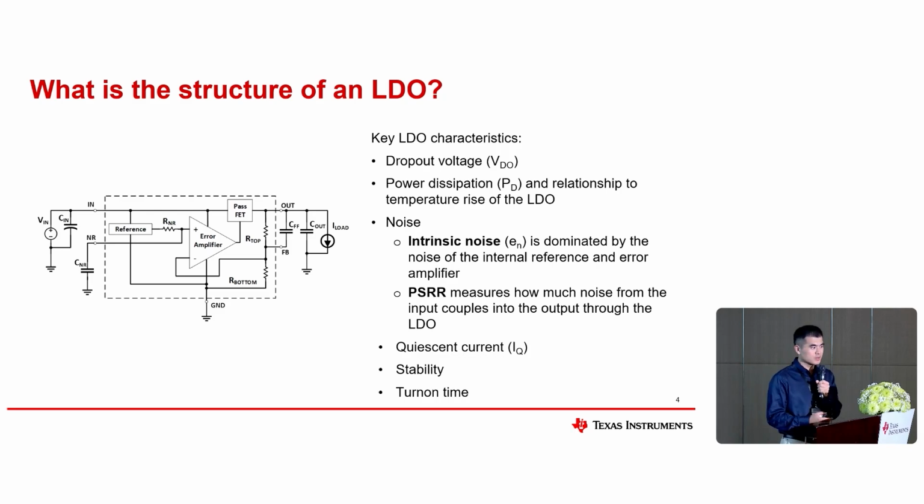For the LDO, there are some key characteristics, including the dropout voltage and power dissipation, because it is related to the thermal rise of the LDO. Also, for noise sensitive applications, the noise, including internal and also external, the quiescent current, stability, and turn-on time.